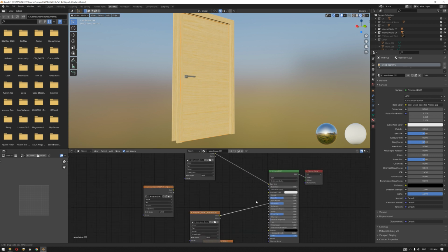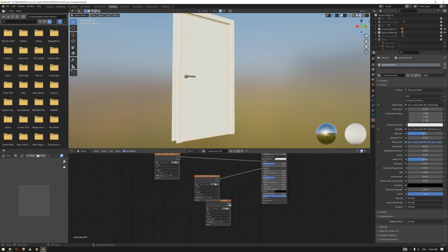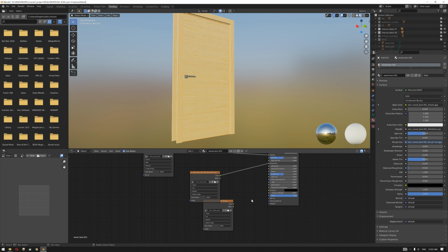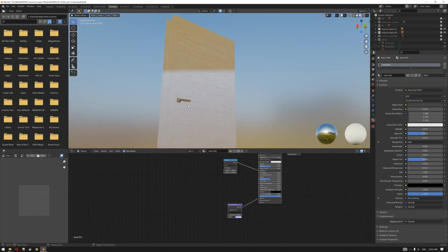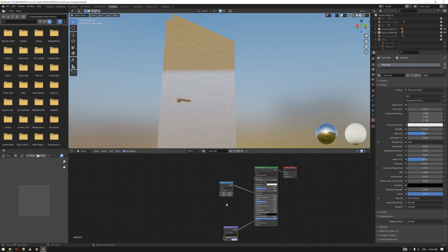Connect all of these so we can export it to Unreal Engine using Datasmith, and then adjust the material inside Unreal Engine as we did before. Don't worry about the reflection, we're gonna reduce that inside Unreal Engine, because the extra node that we can add in Blender will not actually be identified inside Unreal Engine. So albedo, metalness, roughness, and the normal as well.